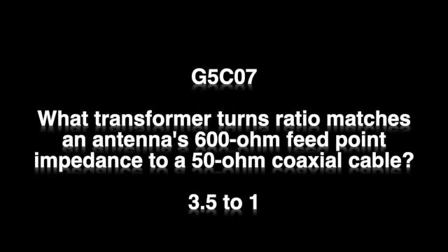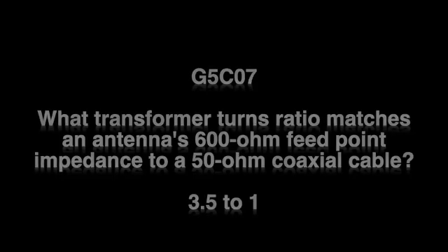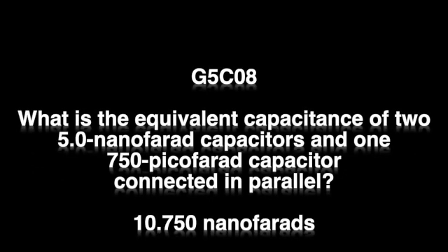G5C07. What transformer turns ratio matches an antenna's 600 ohm feed point impedance to a 50 ohm coaxial cable? 3.5:1. G5C08. What is the equivalent capacitance of two 5.0 nanofarad capacitors and one 750 picofarad capacitor connected in parallel? 10.750 nanofarads.